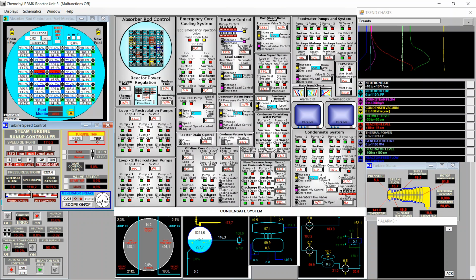We're already at 1k RPMs, and you may see that vibration goes up a bit when we start and we are at several hundreds of RPMs, but this is normal. Probably at these low RPMs we have a lot of resonant frequencies, and when we go above 1000, these resonant frequencies are left behind and the vibration is quite low.